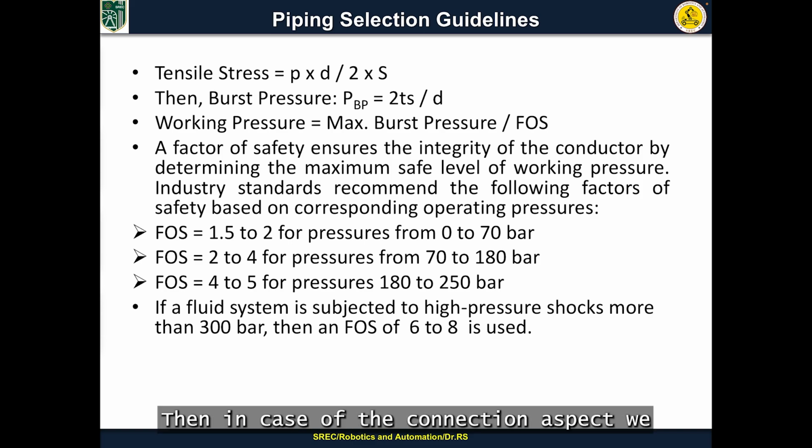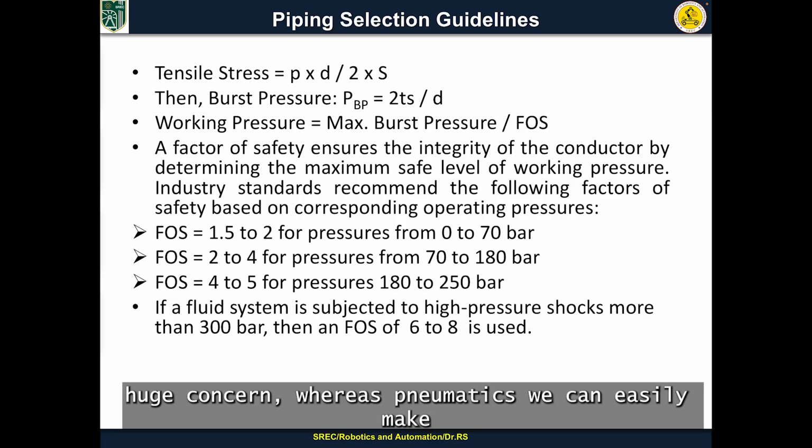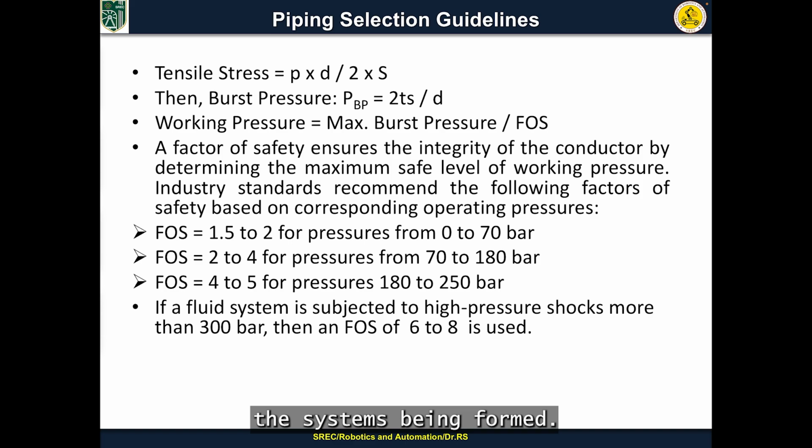Then in the connection aspect, a lot of quick fit connectors are available, so we can easily connect the pneumatic systems using them. Whereas in hydraulic systems, we need rigid connections. We have to use a lot of bolts and nuts along with couplings to connect the connectors. So for the safety aspect, hydraulics requires huge concern, whereas pneumatic systems can easily be formed.